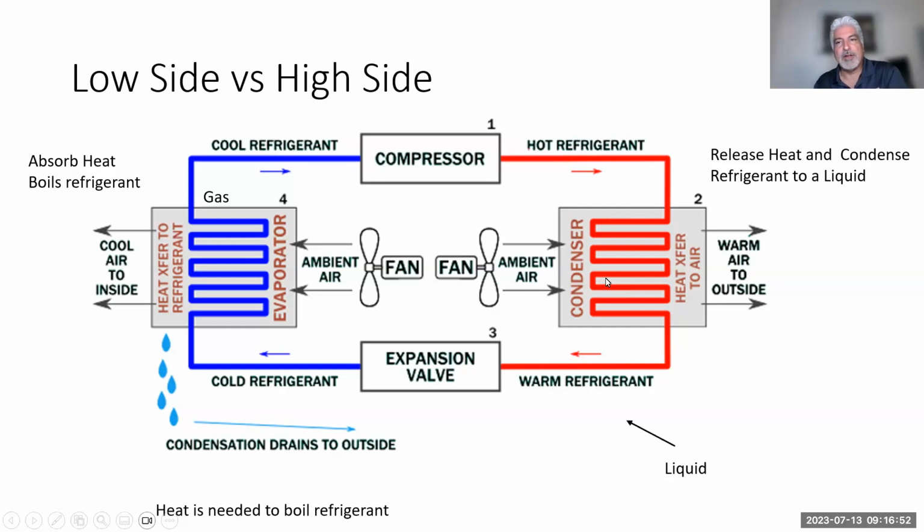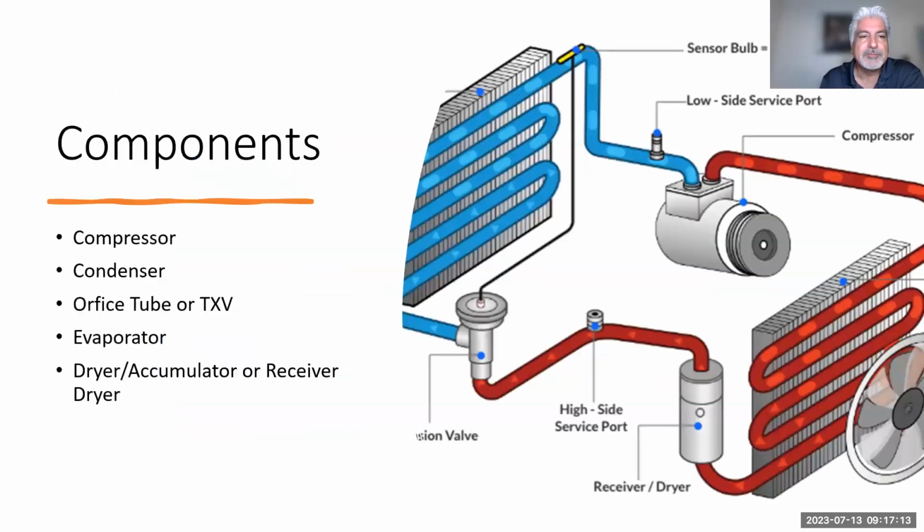Very critical to understand that, because that's where you're going to be dealing with AC systems that are not blowing very cold, even though you charged it properly and checked the oil. Then we need to look at why that is occurring. Could it be an expansion valve stuck or not? But we've got a few video clips that I took yesterday of vehicles I actually serviced, just to show you some readings.